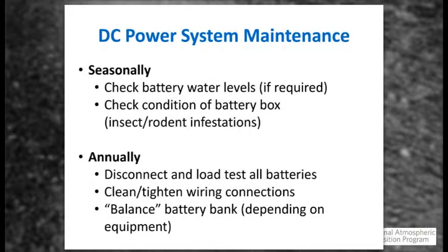Let's go on. Now we're going to talk about some maintenance here, and Jeffrey already highlighted this. Seasonally, if you have a flooded lead acid battery, you'll want to check the water levels. Many batteries have a little sighting in the top that shows the general condition. And then periodically check your battery box. Insects and rodents just love to live in there. It's a little bit warm, so insects can damage the wiring, as well as rodents, obviously.